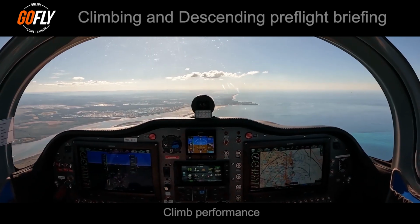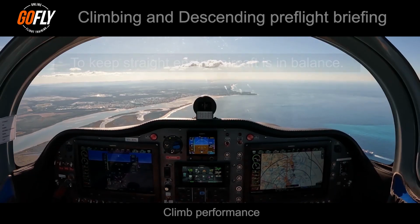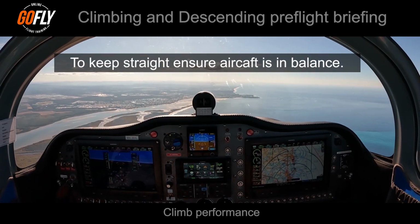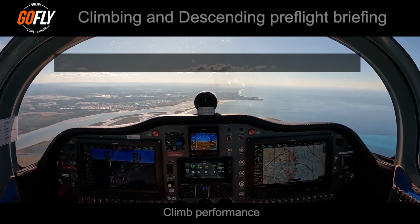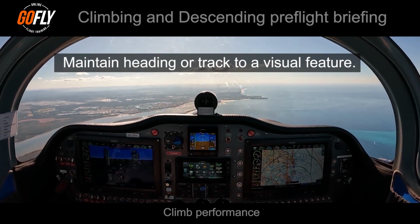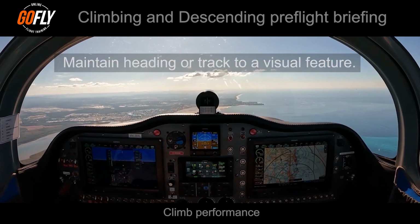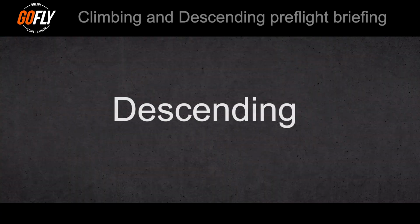It is important that during a climb and descent that we can accurately keep the aircraft straight. We do this by ensuring the aircraft is in balance and the wings are level with the horizon. We also make sure we maintain heading or track to a visual feature. We must also work hard to stay in balance, as this can cause a change in direction.